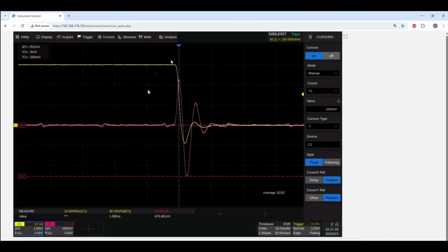Of course, we see something similar on the falling edge. Again, we get undershoot and ringing due to the reflections of this unterminated line. Just for very simple demonstration purposes, we get something very similar on the falling edge. Pretty considerable crosstalk, also due to reflections and ringing, and that's almost at half a volt, which is considerably higher than just going with the slow and more adequate rise and fall times set previously.